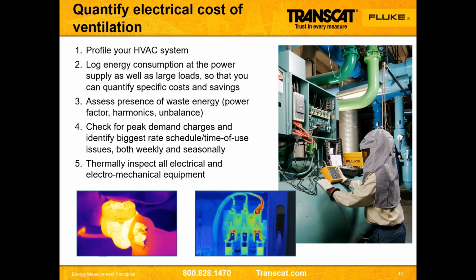So the first part, just like everything else, let's go quantify the power piece. Let's go look at the HVAC panel and let's monitor load over at least a week's worth of time, get an idea how much am I using. And again, how much am I wasting? Am I paying a peak demand charge as a function of that big compressor or pump turning on and driving up my electric bill? And how hot is everything? Is everything inside the operating limits of where it's supposed to be?